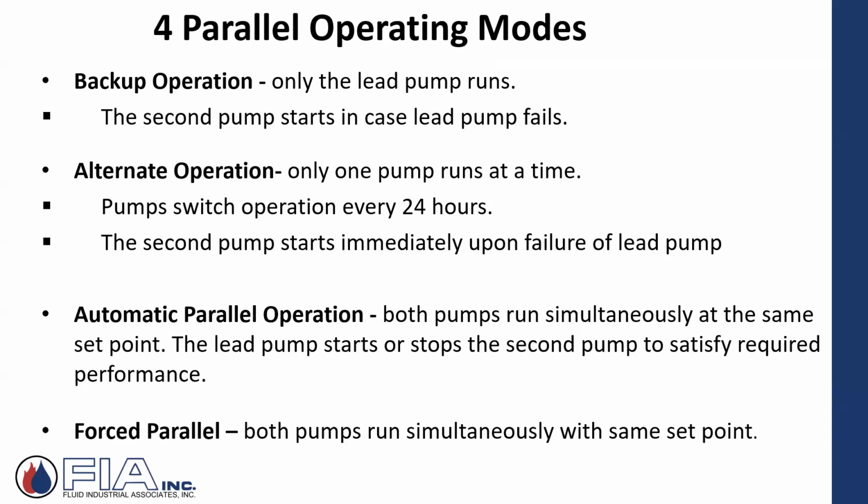I don't want to rotate. Only the lead pump runs. Kind of a weird application, but it's there as an option. And the second pump starts in case the lead pump fails.